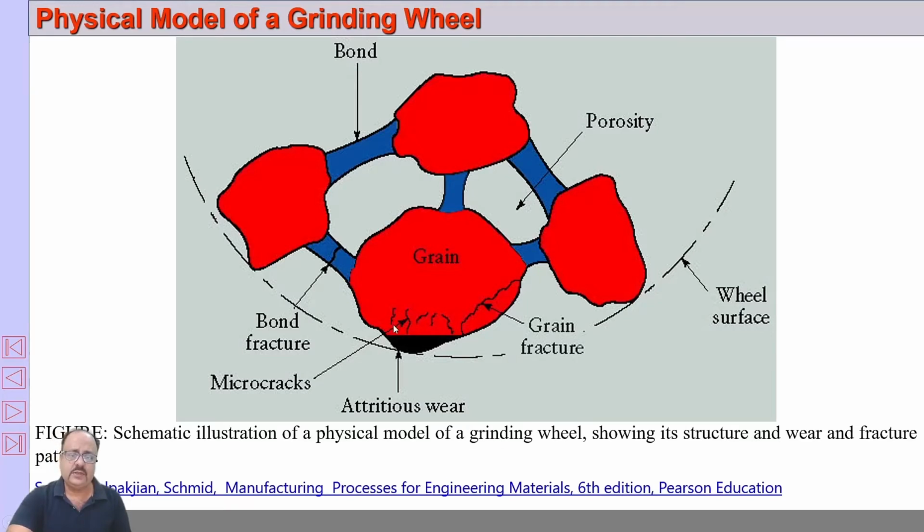And sometimes the contact of the abrasives results in abrasion and diffusion and many other such wear mechanisms, resulting in adhesive wear, and you obtain a flat surface here, resulting in what we call a glazed surface. So all these phenomena occur during the grinding process.